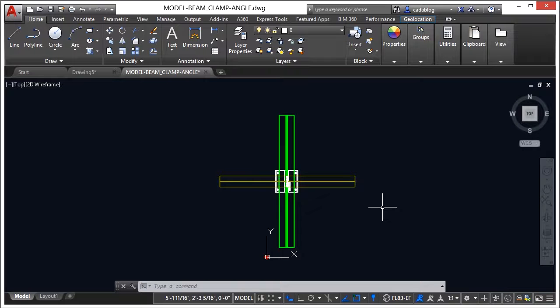Last but not least, I want to talk about some of the under the hood, behind the scenes type enhancements that Autodesk has put into AutoCAD 2017. These are things that you're not going to probably see, but Autodesk has changed the way AutoCAD processes 2D line work and 3D line work to a certain degree. 2D graphics have a new enhanced option, but only if you have a DirectX capable graphics card and hardware acceleration turned on. Your graphics processing unit is very important to AutoCAD.